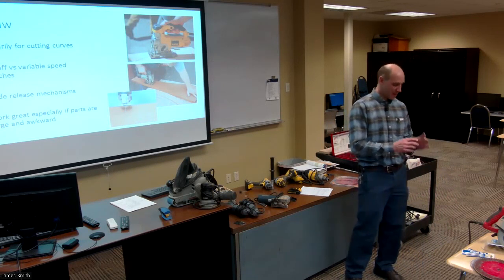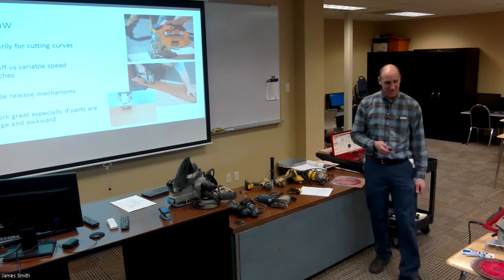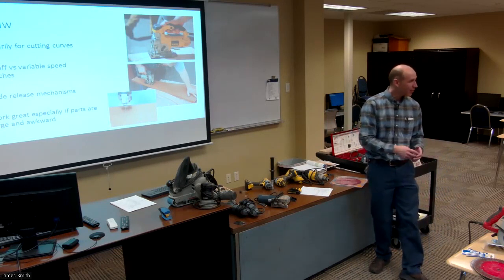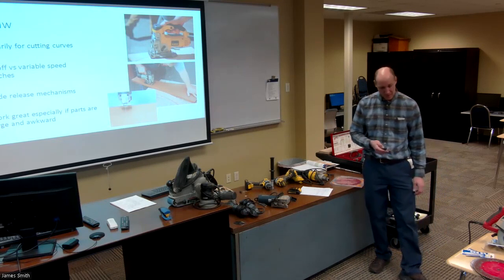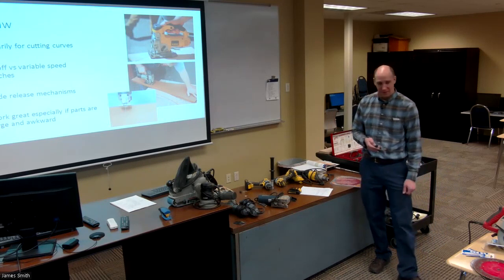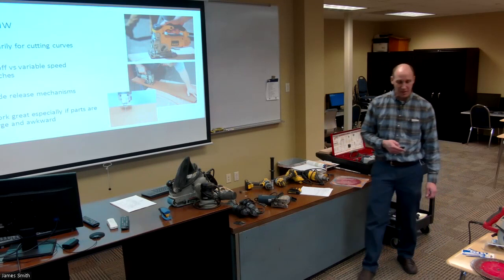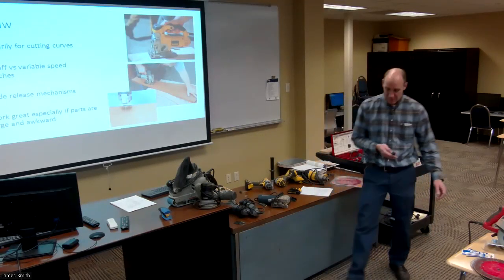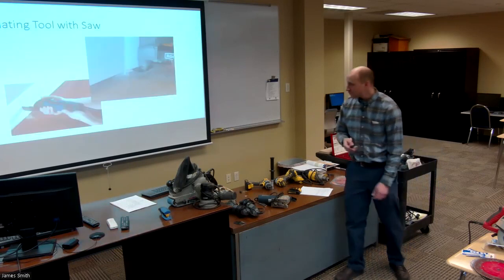Yeah, they make the whole saws sometimes. And you can buy the diamond blades. If you've got straight cuts, I'd use a circular saw with a diamond blade, or one of those wet saws for cutting ceramics. I know when I've put in a couple of tub surrounds, I used the hole saws that have the diamond. Those are good too. But anyway, that's kind of the jigsaw.